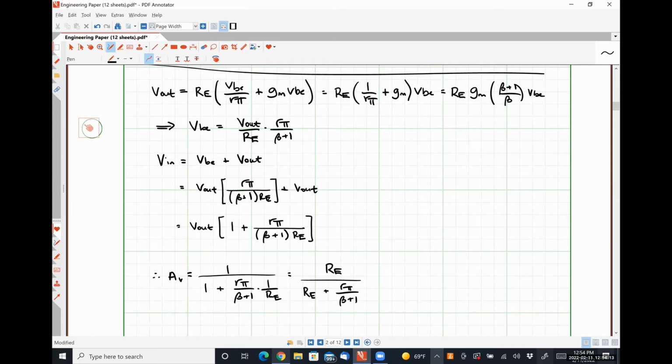Now, depending on how large quantity beta is, it can look approximately equal to 1, right? This amplifier is how you make buffer amplifiers with BJTs. So we have a gain very close to 1, but we're able to add in input resistance and all that kind of good stuff to keep our signal clean. Okay, so this is a buffer amplifier scheme effectively using BJTs.